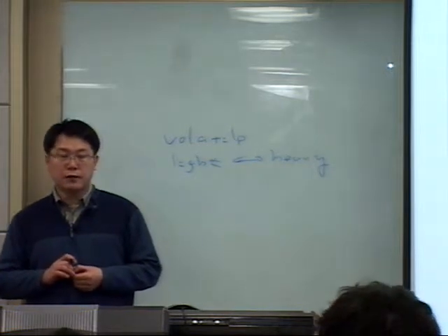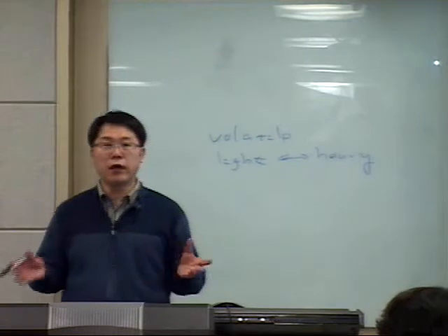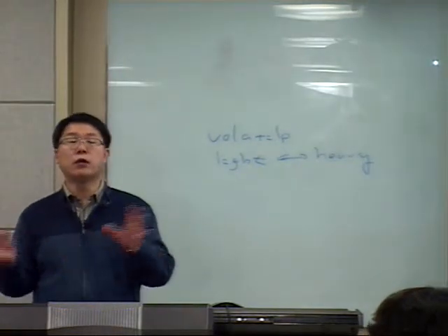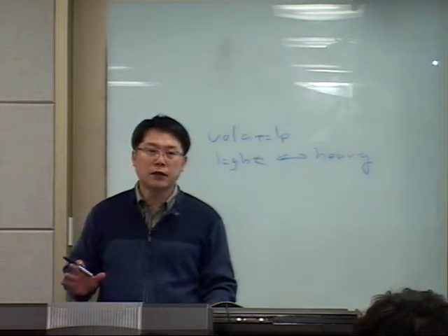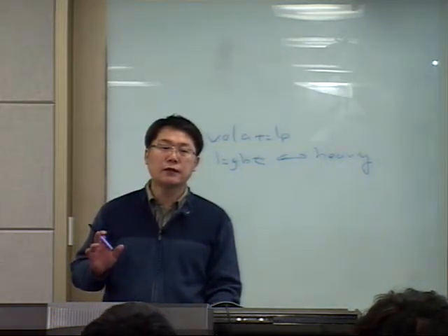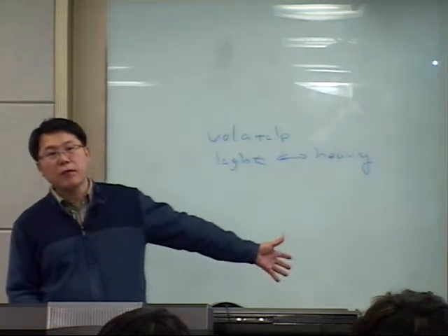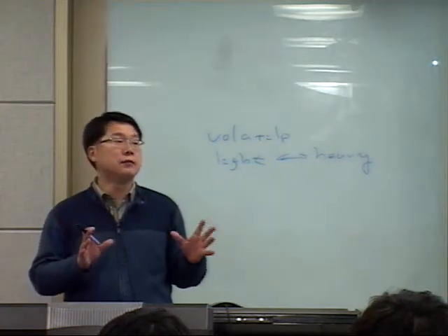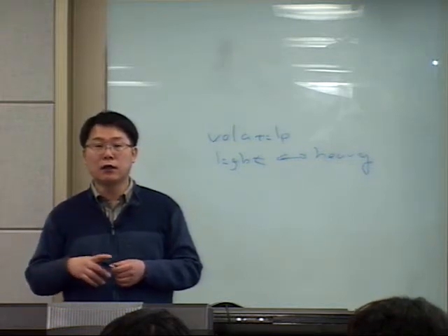Another question is, now BOG is generating, so the easy way is to remove the BOG, but we can get stuck in this kind of situation, that the BOG reliquefaction system is not ready to liquefy the BOG.